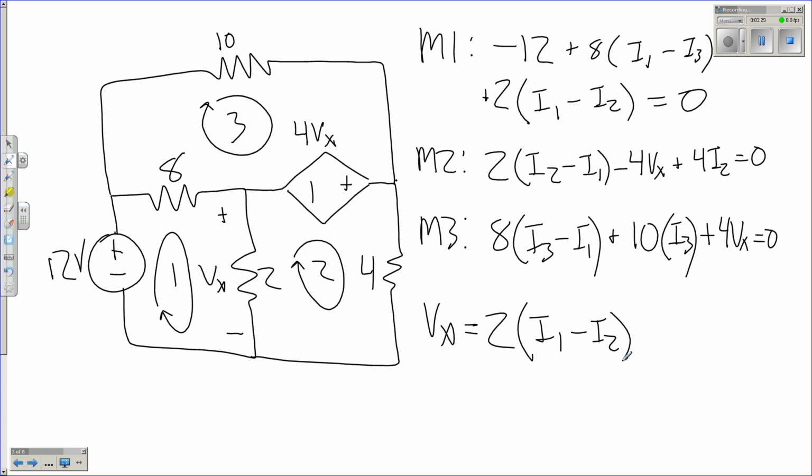So again, voltage sources aren't too much of a big deal with mesh current analysis. And that's really the selling point. If you have a lot of voltage sources, you're going to go for mesh current versus the node voltage, which you might prefer over the mesh current if you had a lot of current sources.